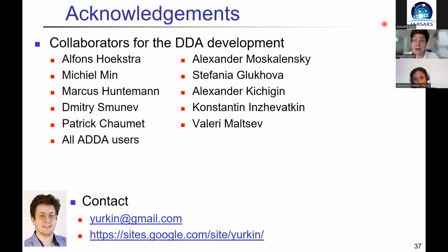For backscattering, the only thing you can tune in the DDA, I think, is the formulation. And I think many people said that the FCD formulation, which I mentioned, I mean, you don't need to understand what it is, just put in a command line option in ADDA, which is written in the manual how it should be, and usually it improves the accuracy for backscattering. But still, you need to just try different options and see the results and ensure that it converges to the threshold of the error that you can tolerate.